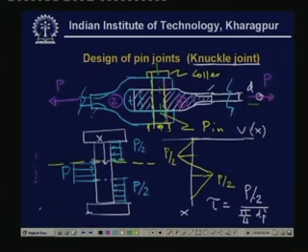Now, we know from the basic theory of Euler beam that the exact distribution of shear stress is not the average, but the maximum shear stress occurs somewhere on the neutral plane, and for a rectangular bar it is roughly about 1.5 times the average value. But for a circular cross section, we have something different.